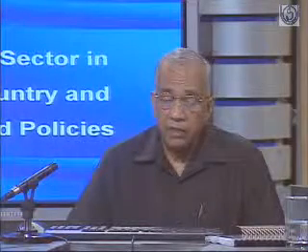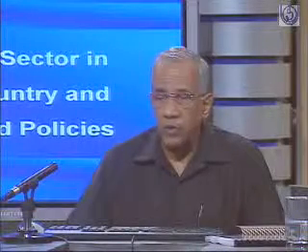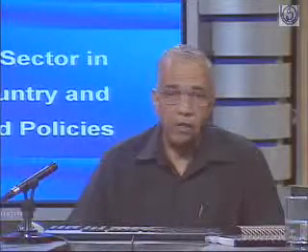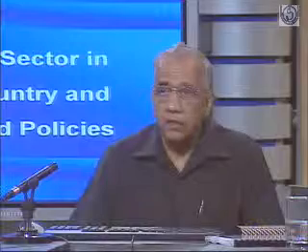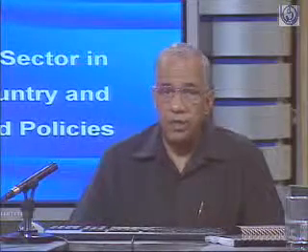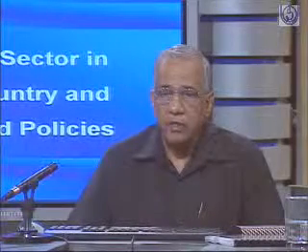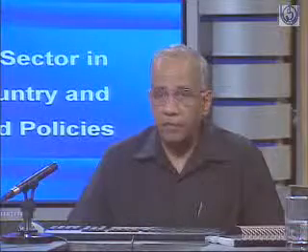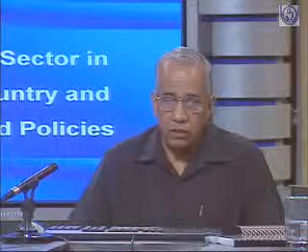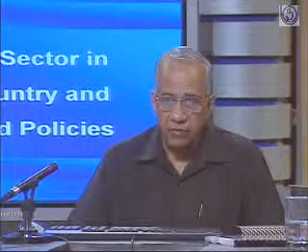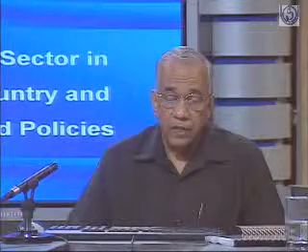And very recently, around the world outside India, the supercritical units of larger unit sizes, 660 megawatt, 800 megawatt, 700 megawatt, have been developed. The development of these units had actually taken place, but we did not venture into adoption of these unit sizes till very recently, since they need training of manpower, a higher standard of water chemistry, and they have erosion problems in the boiler. They are some of the very severe problems once you deal with high temperatures and high pressures in the machine. But then we went in slowly.